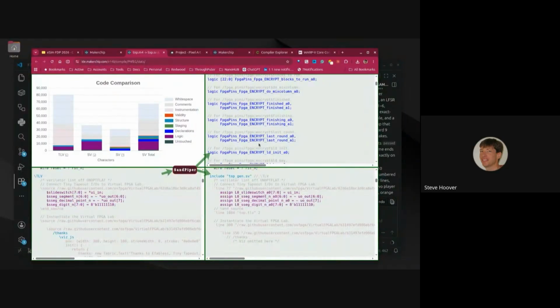HLS is completely unreadable. It gives huge code. When we use HLS, it gives huge code, it's not the same thing. If you were to code this example in Verilog, you would come up with something of very similar length to this. Okay, then I will definitely explore that. Yes, the code that's generated here very closely matches Intel's recommended coding practice. I will definitely go through it, because HLS is really horrible. Right. Yeah, and that's true of most compiled languages. The output is unreadable. That's a definite differentiator for TL-Verilog.